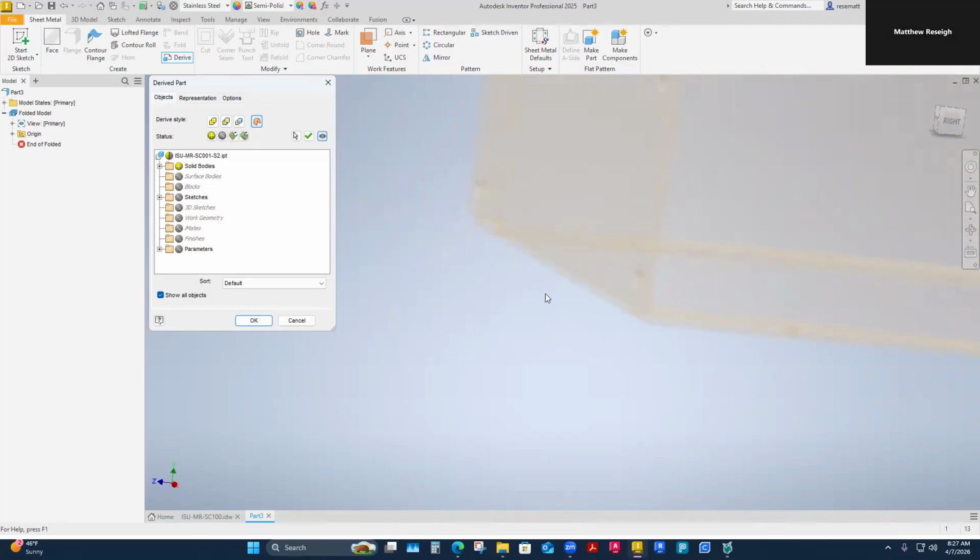But once I bend this flange, this is going to tie in these loose ends. This is a three-sided flange. When I bend the flange on the end plate, I'm actually going to put the hole pattern in that'll complete this square flange. So that's why that's three-sided. My end plate is going to be the fourth side. And we have the sketch for that. When we created this three-sided flange, there's a sketch with where the hole pattern is in it.